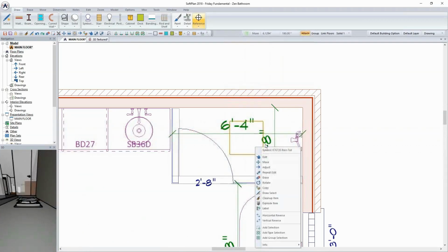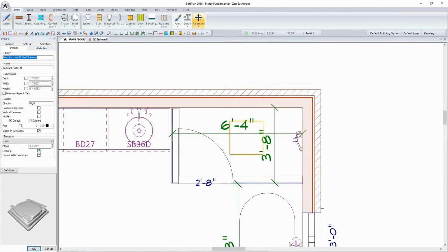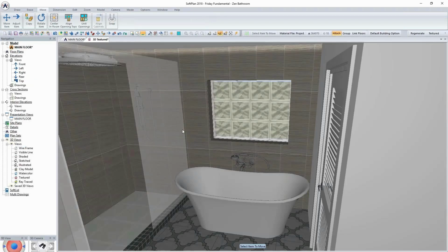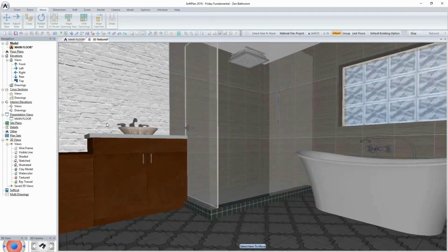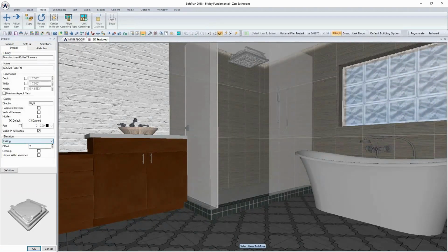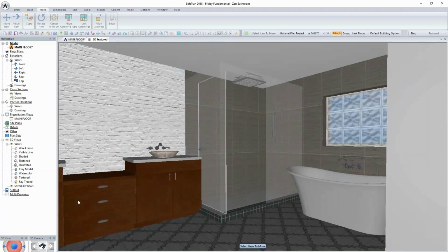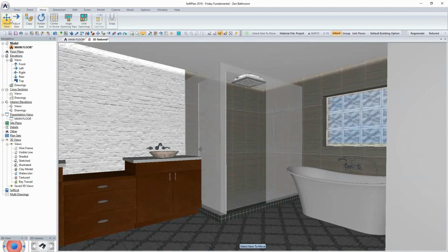And so in this case, as I edit this, I could just go ahead and it's specifically going to the floor. I could also set it to go to ceiling, and with whatever the offset needs to be, push it up or down, etc. And so let me take a quick look. And so there is my rainfall shower head right there. And it probably doesn't need a 6-inch offset on that. We'll just make that a 2-inch and push that up into the plan, or even a 0 to get it set. And so that gets us our rainfall shower head that's going to be there.